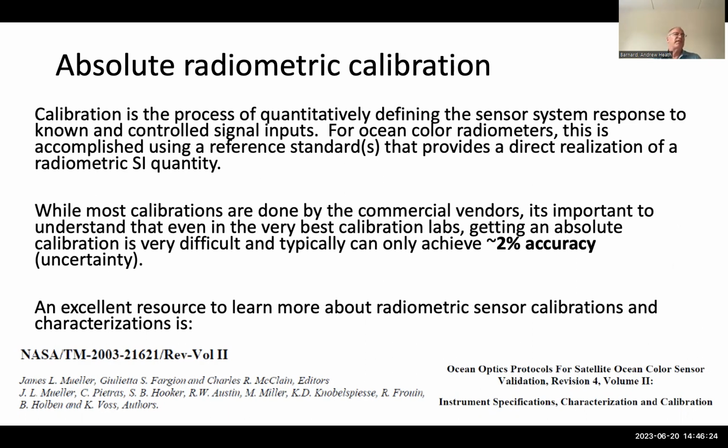While all commercial vendors do their calibration, it's really important to understand, and there are a lot of studies on this, that even in the very best calibration labs, getting an absolute calibration is very difficult. Typically most labs, even the best labs, still have 2% uncertainty in the calibration coefficients and the calibration systems that they provide.